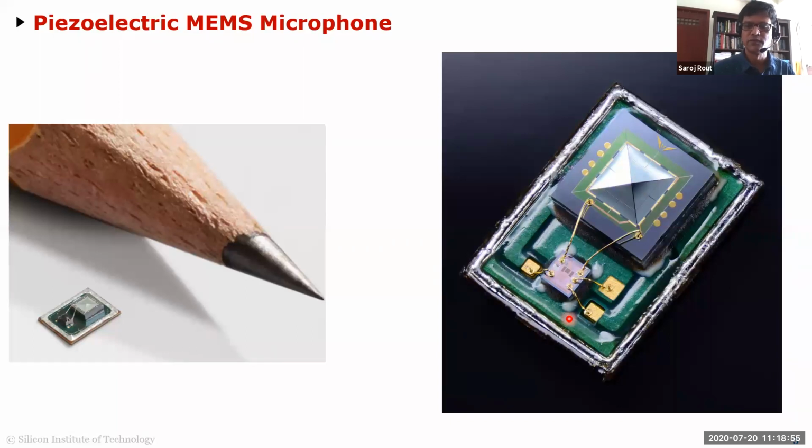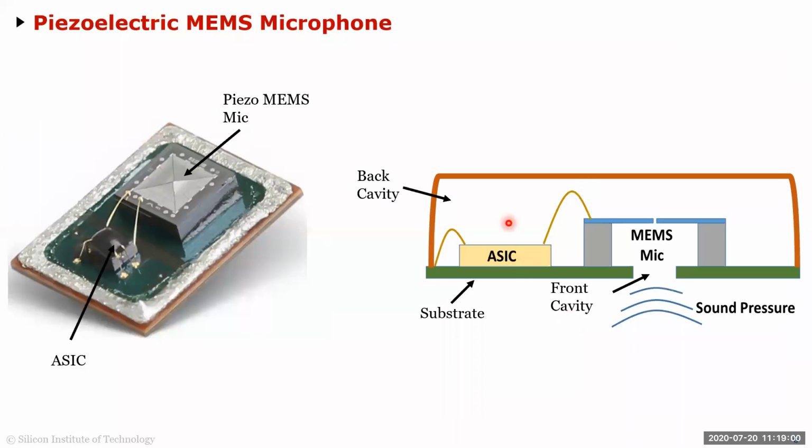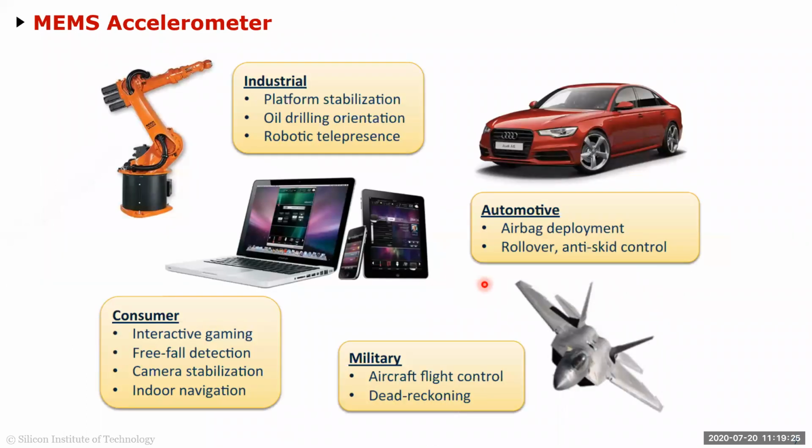So it was started by a professor from U Michigan, actually. And if you look at the entire microphone, that's how it looks like. So the MEMS microphone sits with an opening here. So when you start speaking, your sound changes the air pressure, which vibrates this piezoelectric, which generates a voltage. And then you have this VLSI chip, which converts that voltage into electrical current or whatever it is, and digitizes it and sends it to the processor. And that converts into all the signals you need.